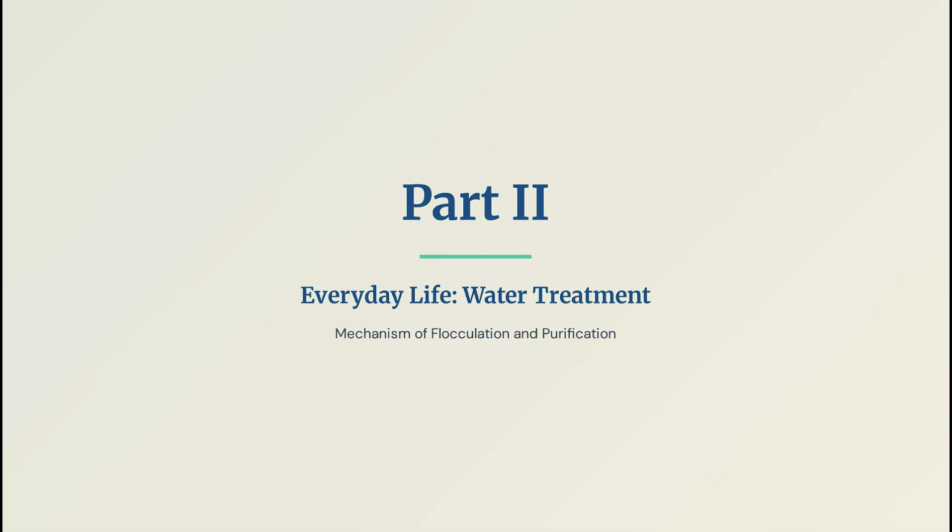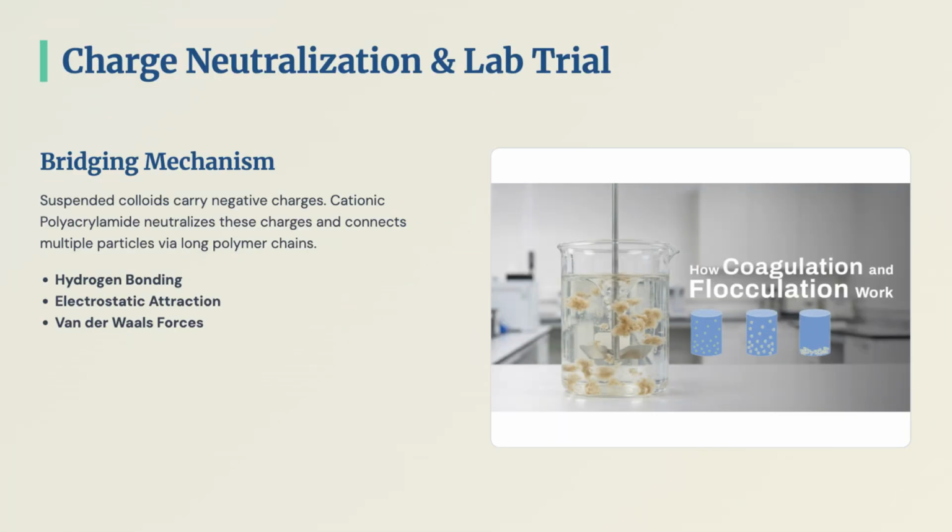Next up is everyday life. Water treatment. In the process of coagulation and flocculation, tiny suspended colloidal particles floating in water usually carry a negative electrical charge. Consequently, they push each other away. This electrostatic repulsion makes it incredibly difficult for them to clump together naturally.